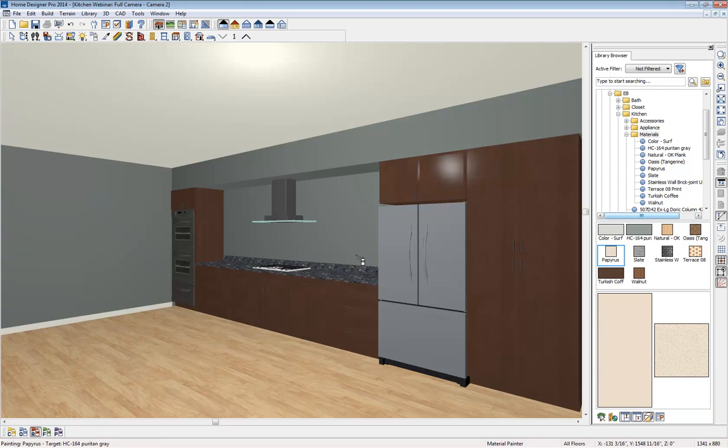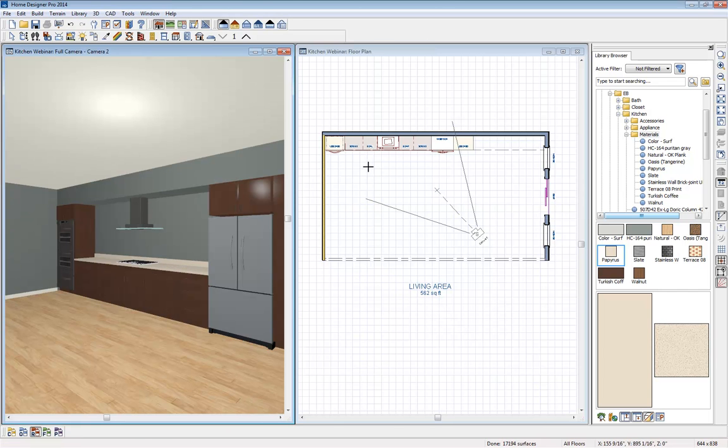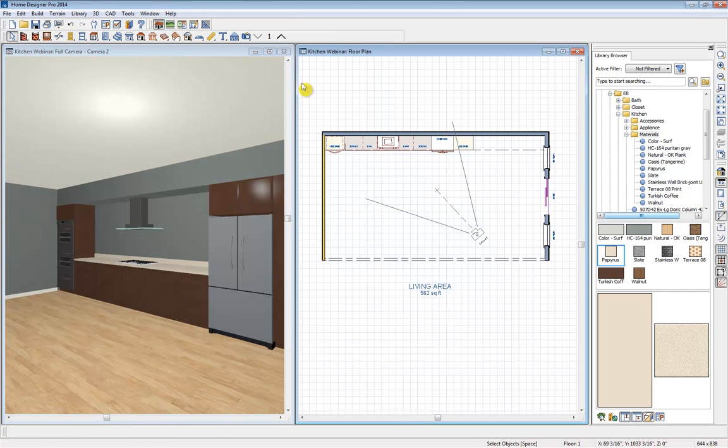Alright, so now with our countertop, let's lighten that up a little bit. We're still in room mode, so with one click, that will be applied. Now I'm going to get into some different shelving. Let's put some shelves on our wall here. So Shift F6 will get us into our dual view. And we're going to get back into our cabinet tool and select our shelf option.